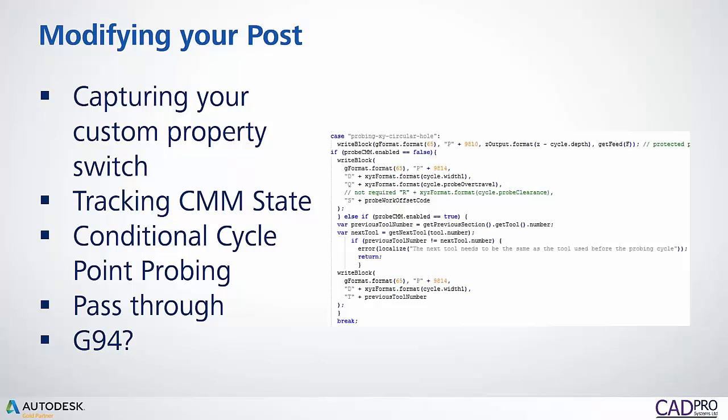So it's worth mentioning that we calibrated the Renishaw system before doing this, and that tolerance, compared to what some of you might work to, that tolerance of what was it, 0.02 of a mil, was fairly coarse. So in that kind of range, this was perfectly acceptable. If you're down to the thousandth of a millimeter, then you might have to rethink things.